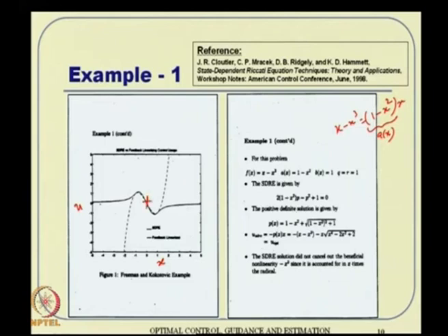Both are fairly close to each other around the point, but as the deviation becomes larger, the feedback linearizing solution quickly diverges to infinity. That means you need a very high amount of control compared to the optimal control. In fact, optimal control just stabilizes to a finite value close to 0, and it goes to 0 when the deviation becomes large.